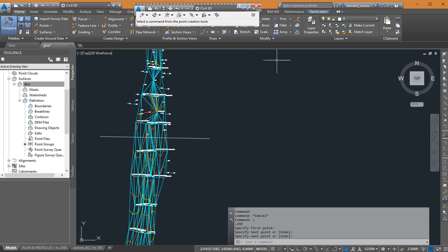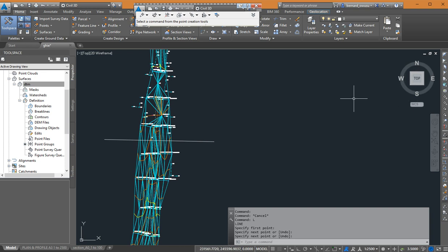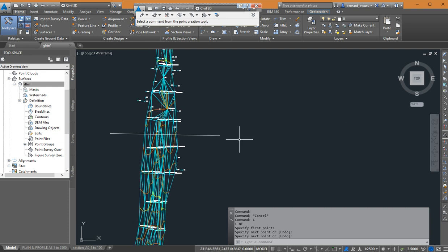So please, what we are going to do is that we are going to divide our screen into two, so that I have two viewports for the model space. Please, are you getting what I'm saying? So that we can see the plan and also the cross section that we are going to do. What we are going to do is just a quick profile. It's a temporary profile. The moment you save the file, it goes, or if I should delete the line, it also will go. We just want to appreciate what I mean by the break lines, how the break line will have an influence or effect on the surface.